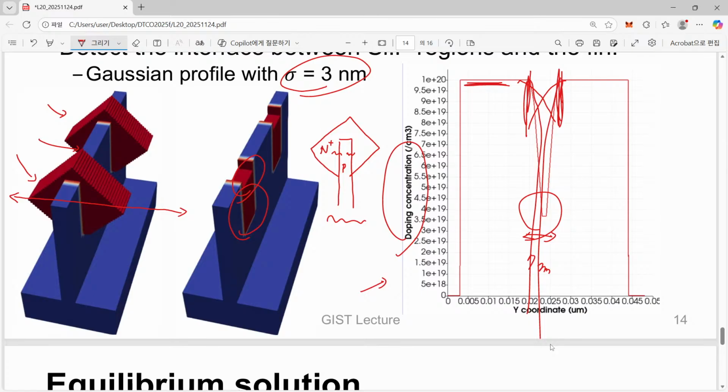So simply speaking, although you have drawn a 20 nanometer gate, the effective channel length of your transistor becomes shorter and shorter, and that will introduce worsened short channel effect. So you want to reduce source drain resistance, but if the cost of that engineering is worsened short channel effect, then you cannot afford it.